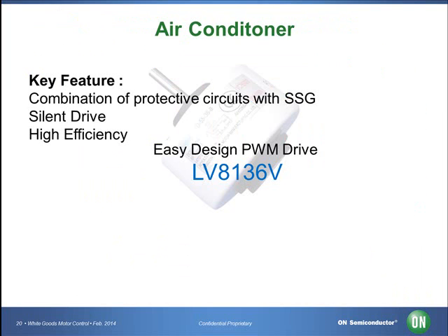Air conditioner motors are driven by high voltage and are required to be highly efficient and silent in order to provide a positive consumer experience. To optimize efficiency and to keep noise at a minimum, we recommend a product like the LV8136V, a PWM drive from ON Semiconductor, which is a 3-phase Hall sensor controller.